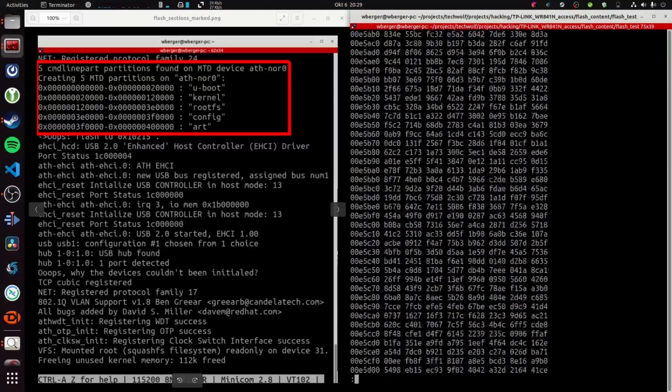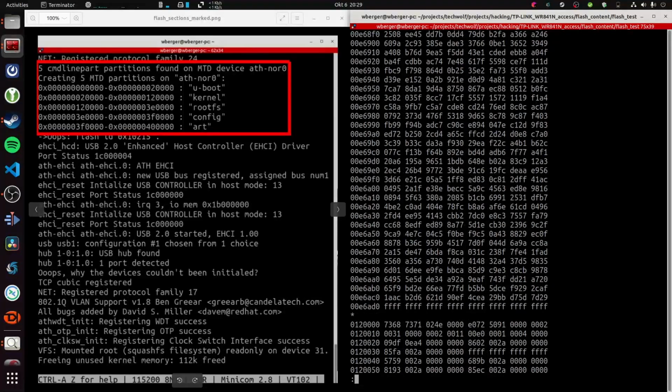If we go back, you can see the kernel image ends with this line. But this line is far away from the final offset where this section ends. So that means it can be declared, but for future updates, for instance, because rootfs will always start there, you still have space in case you want to update the kernel. Everything is erased and written by FF, and then maybe the kernel image goes a few lines longer.